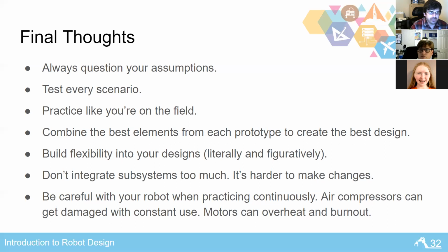We really want to be able to switch our mechanisms out pretty quickly. So finding some modular way to design how a mechanism bolts on will really allow you to get things on and off the robot faster, which makes the drivers happy because they have more time driving the robot. It makes you happy because when something breaks in competition and you have a full spare mechanism that you can bolt on, you don't miss your next match because you're having to fix the robot just because you made it so hard to attach.